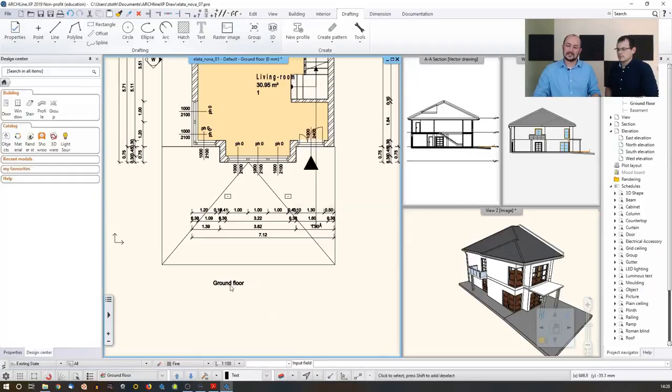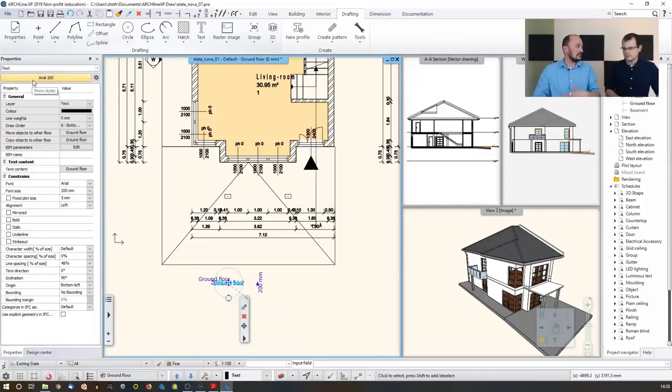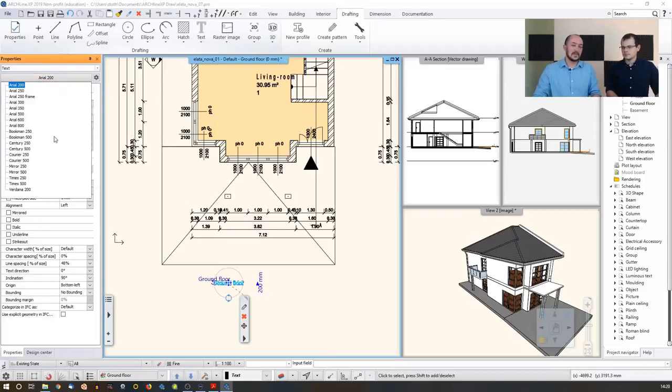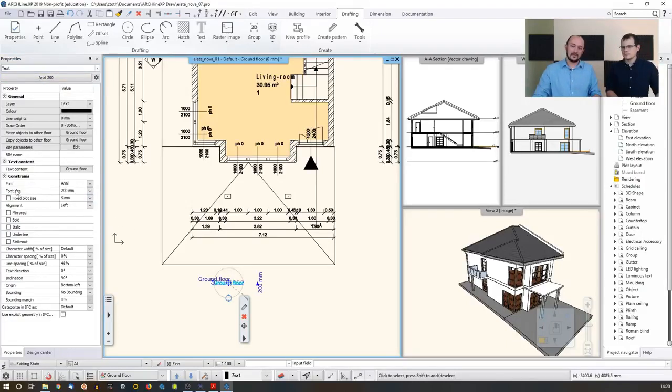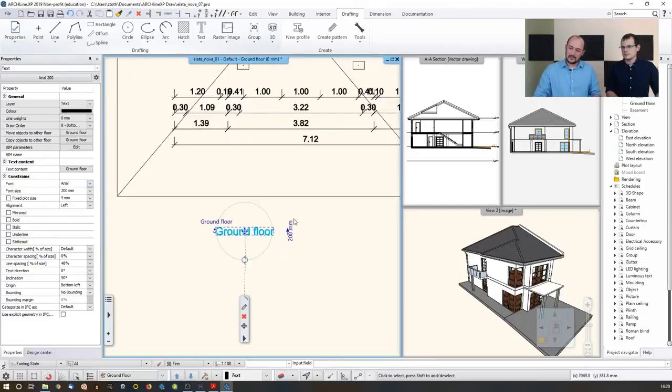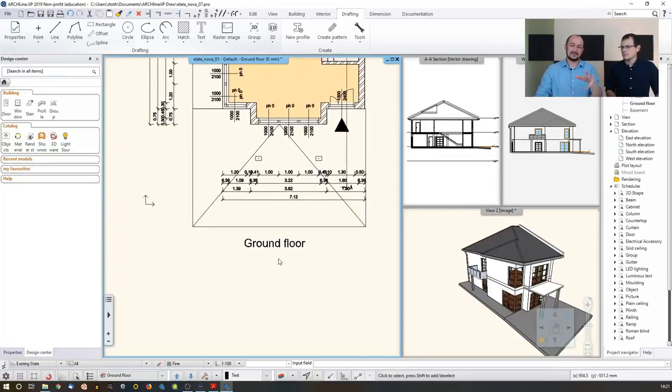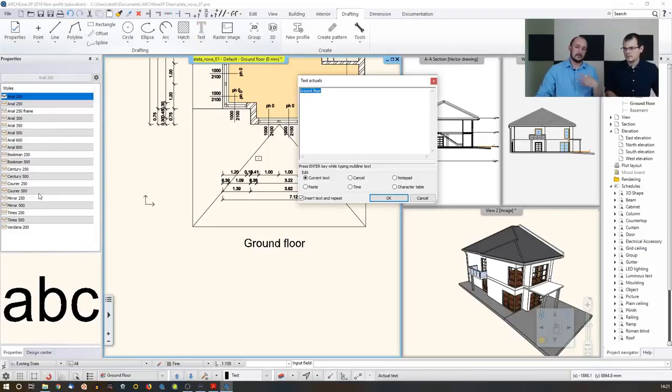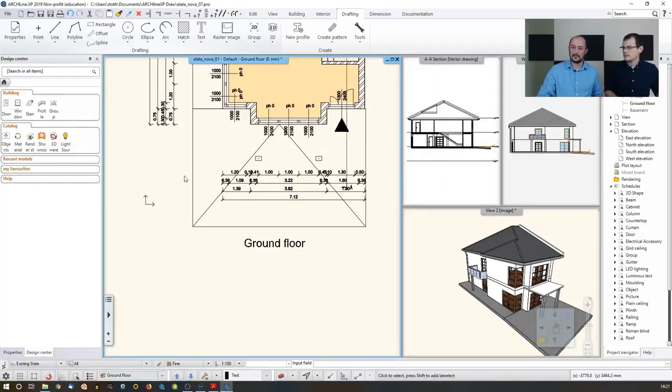I'm not satisfied with the size, so I have a few options. I can just change the type, I mean the style, selecting another one, or I can just edit the height, which can be edited here. And also, if you zoom in and take a close attention here, you can see the height. Actually, it's 200 millimeters. Let's just double that to 400. And hit enter, and now it's just larger. So it's just this way you can select any sort of text and rescale it. So this is not a global setting. No, this is the case-by-case setting. No, it's just I have only changed this one copy. But if I select and place another text next time, it comes again with the settings that I'm selecting from the left-hand side.